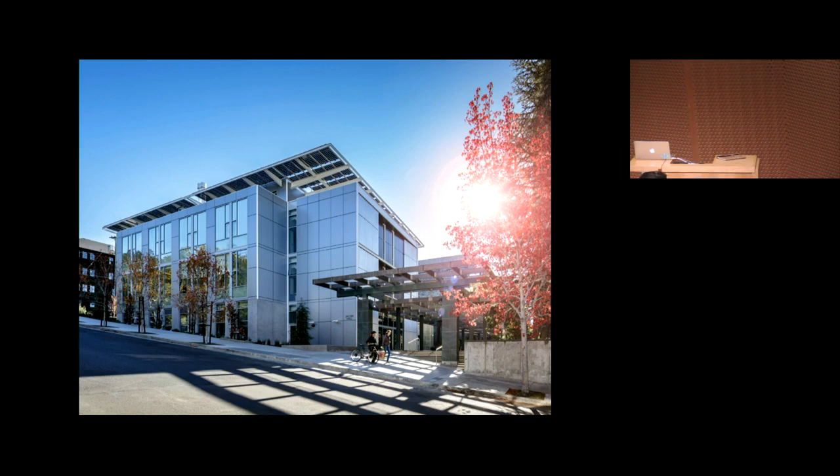Yeah, so the answer to the first question is absolutely. Happens to be not my student, but Eric Paulus, who's another faculty member at Berkeley. His student, Kevin Tian, has a whole library of different components which he 3D prints on the Voxel8 printer that came out of Harvard, where you have the ability to deposit conductive material as well as non-conductive material. One interesting challenge is that mechanically the conductive parts are not that stable. So if you have a lot of contacts, after 100 actuations or so, they'll just rub off. But that's just another design constraint. So I think here the design constraint is how can you design interactive elements that are 3D printed where the conductive parts are never in actual direct contact. So you look at different ways of sensing.